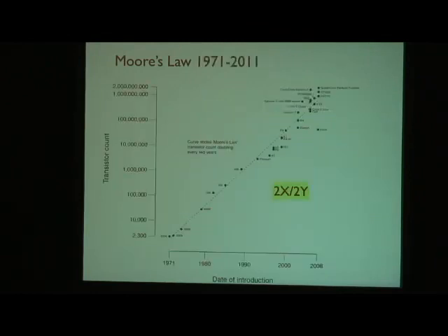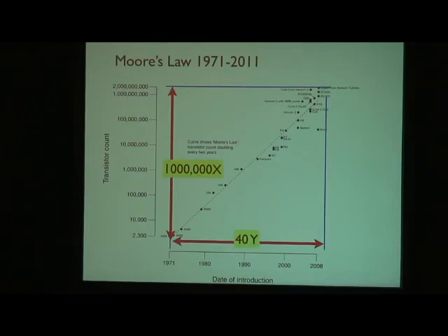Now, going back to the CPUs, this is a chart from Intel Corporation that shows how their CPUs line up perfectly on Moore's Law. The latest Sandy Bridge Romley chip is 2.3 billion transistors, and the Intel 4004 in 1971 was 2,300 transistors. Now, Sandy Bridge was actually shipping early access in 2011. So in the last 40 years, which is 20 doublings, 2 to the 20 essentially, we did see this million-fold increase in transistor count, which is nothing short of amazing. In fact, there hasn't been anything like this in the history of mankind.